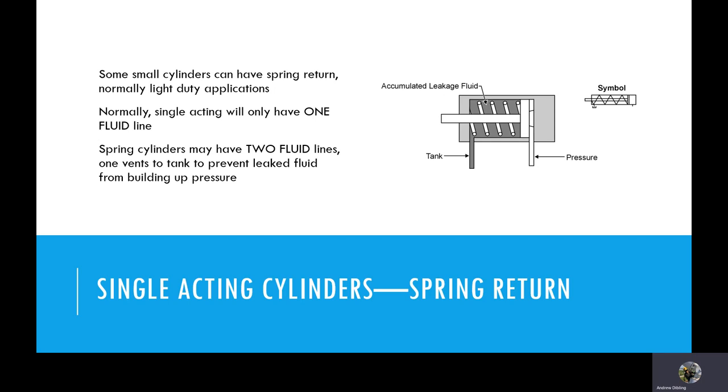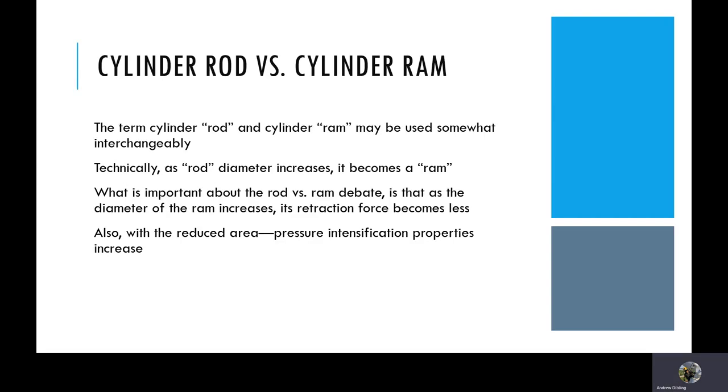But these cylinders will have a return spring. The return spring will, of course, counteract that force, similar to a dead weight from gravity, and retract the cylinder. The amount of force applied can also be controlled by adjusting that spring. Because of Hooke's law, the further you compress a spring, the more it pushes back against you, so it can actually be a very useful element in that.